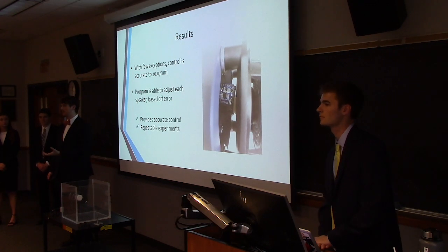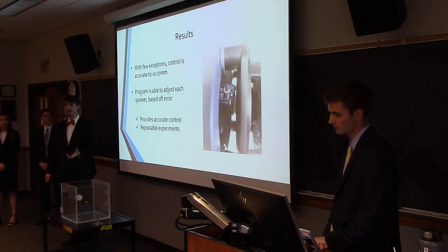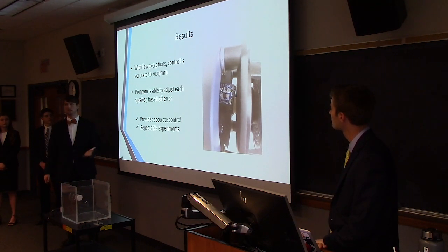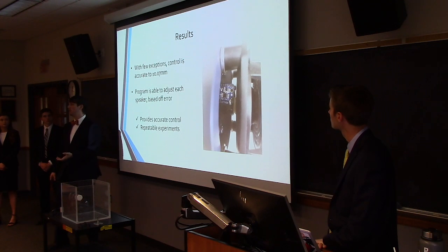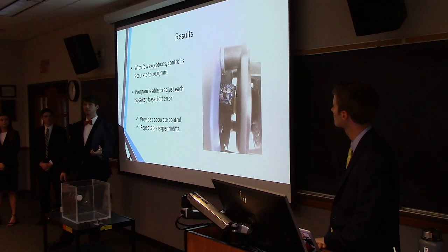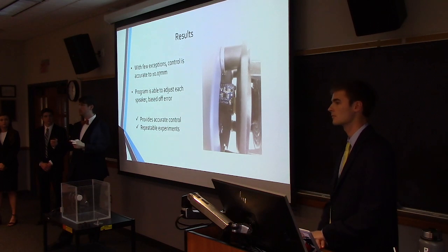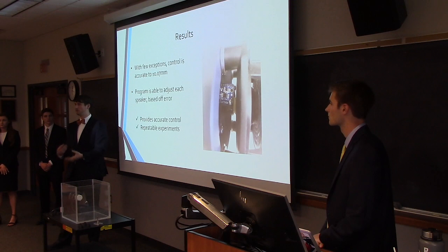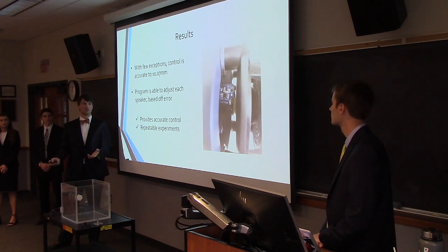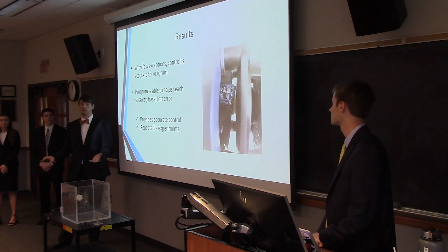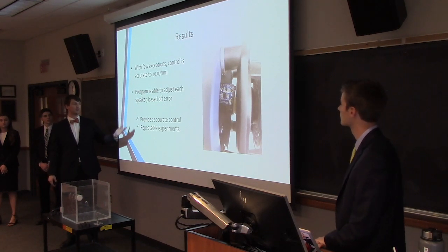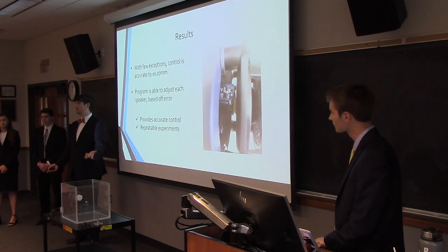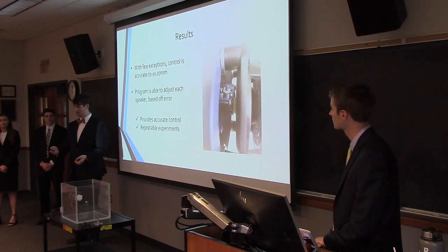It means that we know the control system is functioning properly and is actually doing what it needs to do. We also know the program is able to adjust for each speaker. This is a huge improvement over the previous year's turbulence tanks, which relied on just sending a certain voltage. Instead, we're guaranteed that we know what stroke is outputted, which means we're able to repeat these experiments, because if we just send a voltage, we don't necessarily know what the speaker is going to do. So we're able to provide accurate control using the program, and also do repeatable experiments, which means it can actually be used for what it's trying to do.